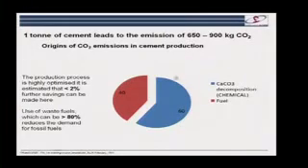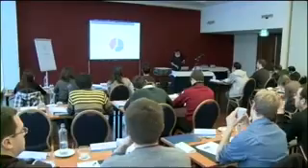So where we need to look is on this side, this 60% of emissions here, and this is more problematic. This 60% here comes from the dissociation of calcium carbonate. So as we'll see later, the main ingredient to make cement is limestone, calcium carbonate, and the first step in the production of cement is to heat this limestone up, and it then dissociates into calcium oxide and CO2.